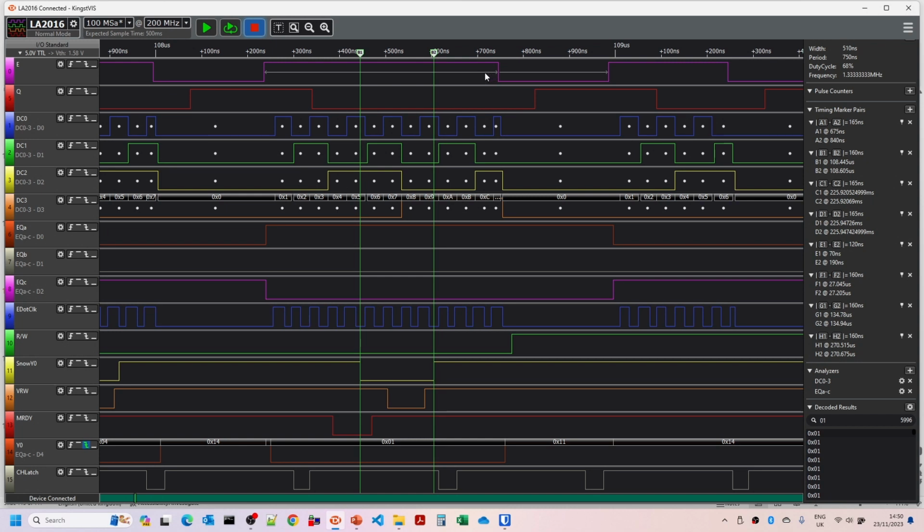The number of times that we end up with this stretching circuit working is not that often, so it's not going to have a dramatic influence on the performance of the system. And so you can see here where I've drawn the timing markers on either side of our Y0. You can see below, this is what the Y0 signal would be. However, the normal Y0 signal would stop at that point there, because it would only be as wide as the E signal normally. And you can see now that the boundaries of where the character latch is here, that the Y0 signal fits comfortably inside there, and then the write signal in there as well.